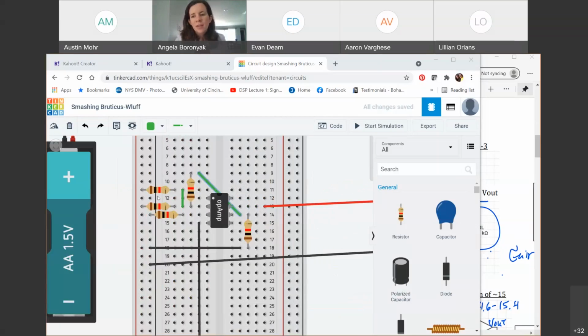Yeah, they're in parallel. And they look in parallel even geometrically, but circuit-wise parallel means same voltage on this side, right? So all connected. Same voltage on this side because I've now run a wire. So if you wanted them in parallel, that's okay. If you don't want them in parallel, make sure you're actually hooking them up in series instead of parallel. Do be very careful with that.